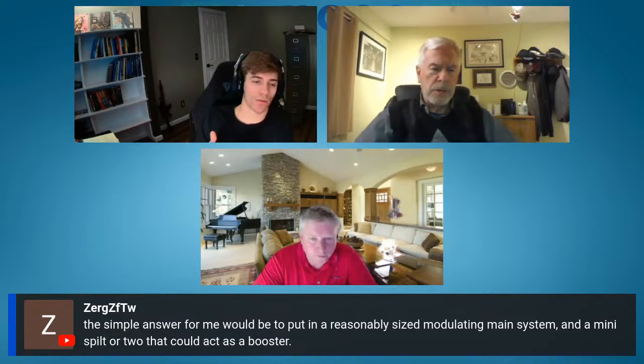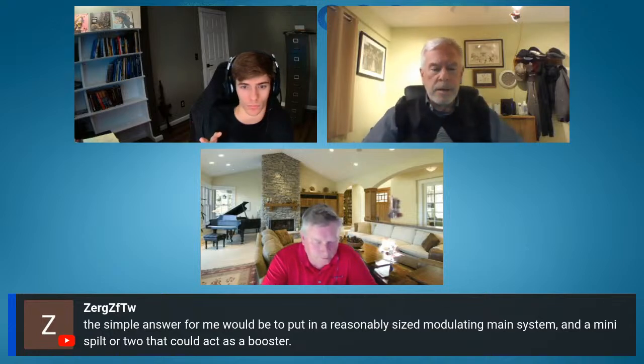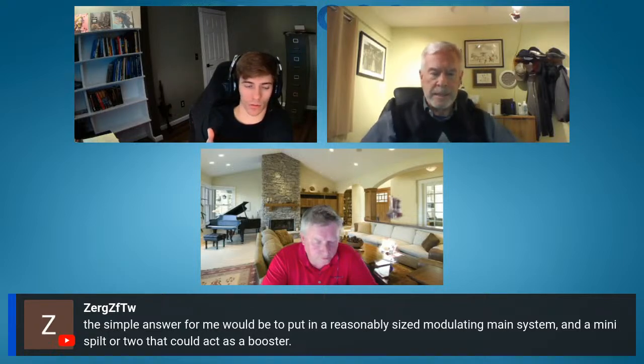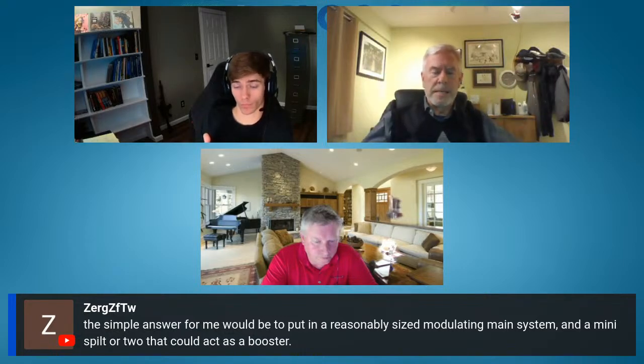Okay. Thanks, Doug. So yeah, go with a smaller system and offer as an option some ductless systems that they could kick in when they needed it, if they felt they needed more capacity. It may happen that they never do. Just offer the minis as an option to be put in later if they need it. If they don't need it, they'll be surprised and pleased.